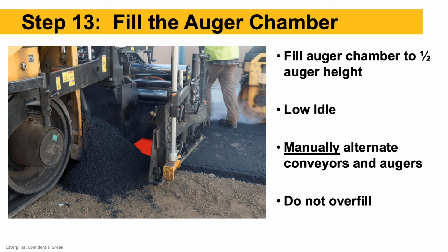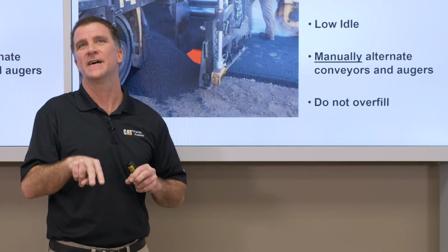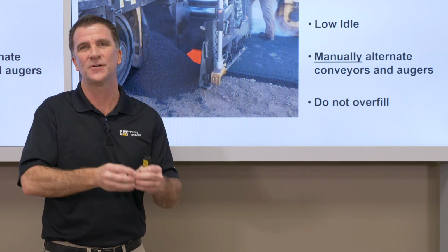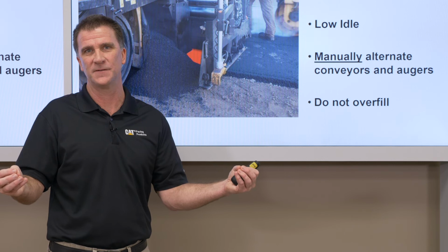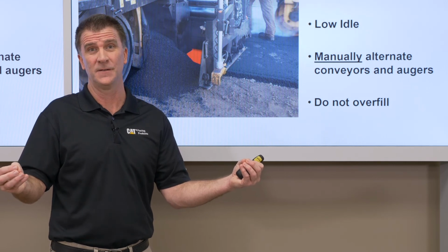We want to do it with the paver in low idle. One mistake I see crews make is the paver operator wants to be nice and friendly to the guys down on the ground. So he'll manually feed that at high idle and literally overload that screed to start with.